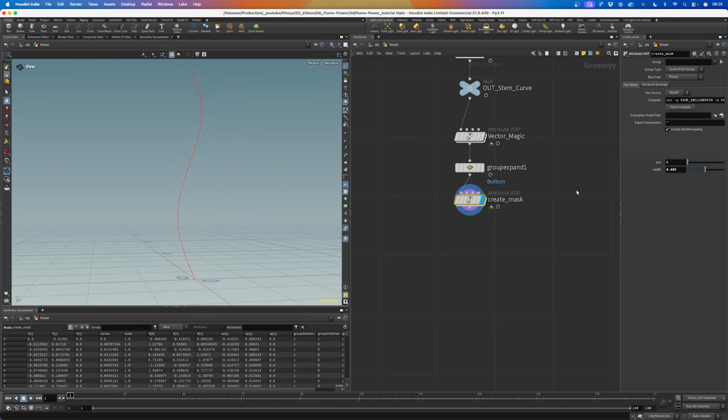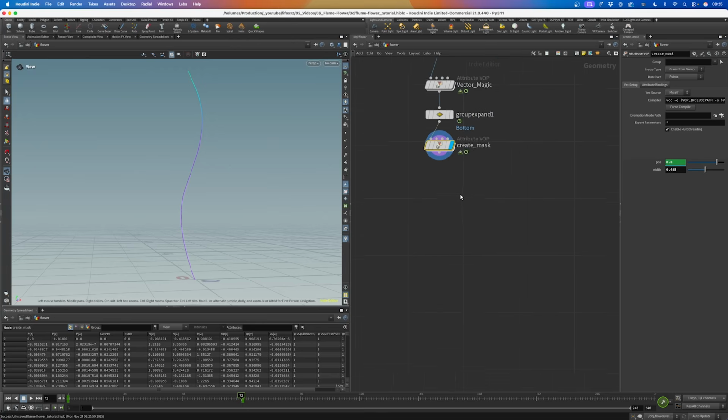Let's do this by holding Option, click in the first frame here, and let's say over 72 frames we want to arrive. Maybe not at 1, but at 0.9 maybe, or 0.8. Yeah, maybe 0.8, because we never want the top part of the flower to be fully grown. So there should be this kind of tapering shape of our blossoms going upwards. Cool. This is our mask attribute.